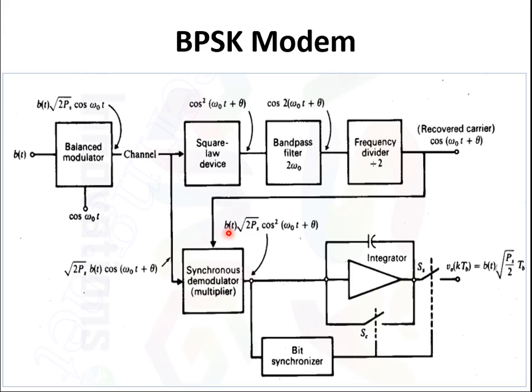So you can observe it looks like once again a modulated signal multiplied by cos theta. Yes, cos square theta, that's fine. But what can you write for cos square theta? It is 1 by 2 times of 1 plus cos 2 theta, right? So that's exactly it. After this I'll be applying it to an integrator. Actually, an integrator is a low pass filter.